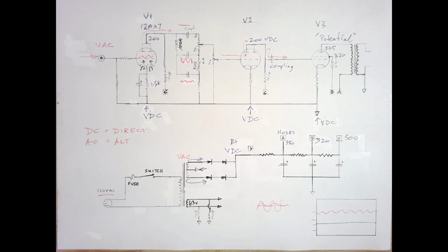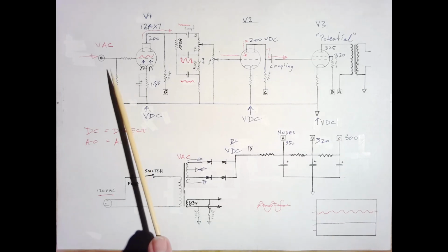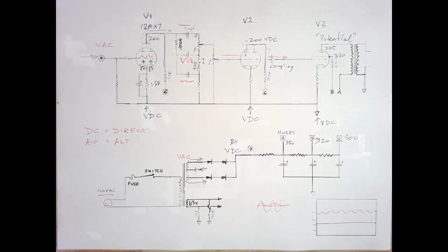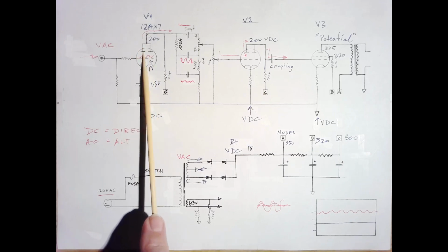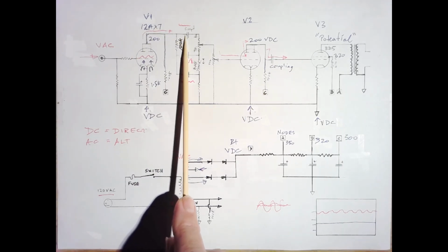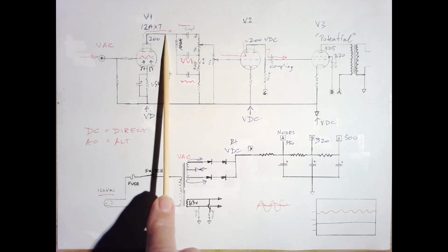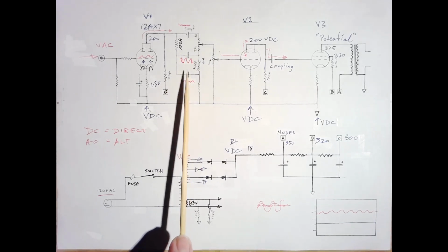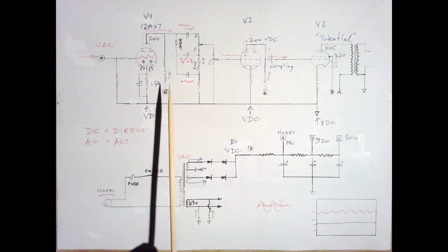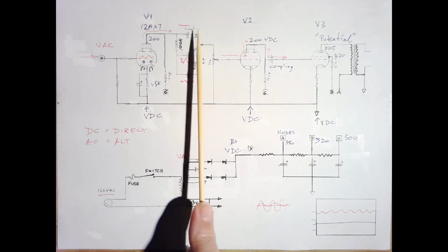So moving along, I look at the DC voltage as an invisible platform throughout the circuit over which the AC rides. It floats on top of it. And they're quite separate. They don't mix and mingle. You might think the two would mix and mingle, but once they're separated in here, they can't go the same places. For example, our AC current will get amplified here and pass up through here, and it will pass through our capacitors. But the DC load that is sitting on here is also sitting on here, and it's coming to that point, and it's passing through this and coming to that point and down to this point, but it can't go anywhere. All dressed up and no place to go, because capacitors, simply by the physics of what a capacitor is, block DC voltage, but they allow AC to pass through.